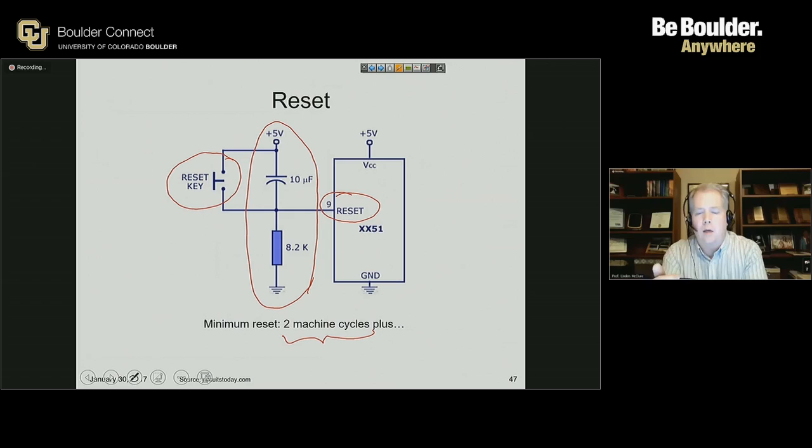But in a design, what you might do is you're going to build a whole bunch of systems and you start characterizing them. You start taking a look. How long does it take this system to come out of reset? And is there any tuning I need to do to my oscillator circuit? And once I've determined what the startup time of my oscillator looks like, then I can choose my reset values to ensure the processor stays in reset long enough upon power on.